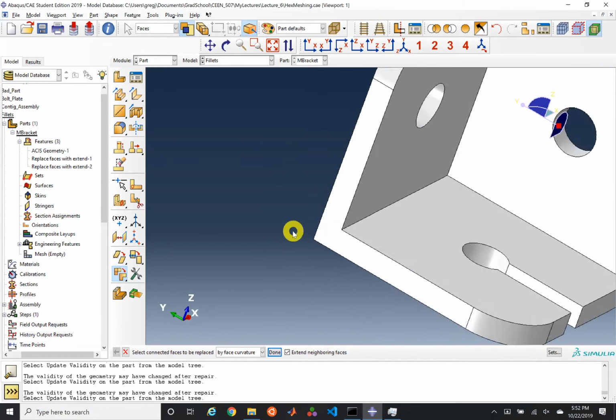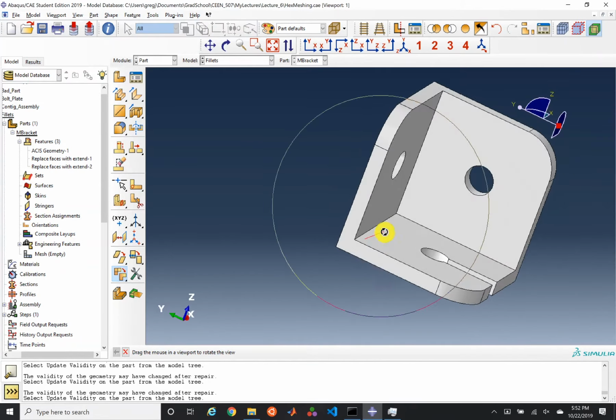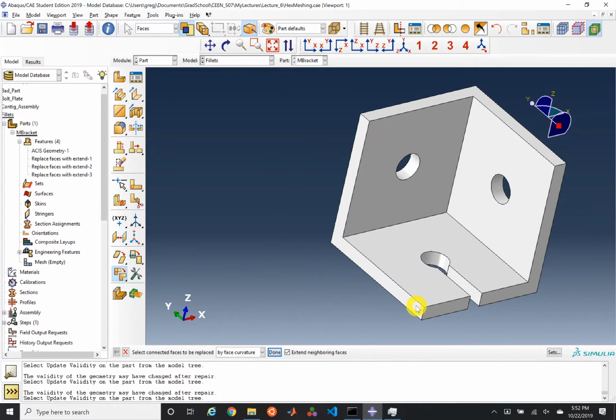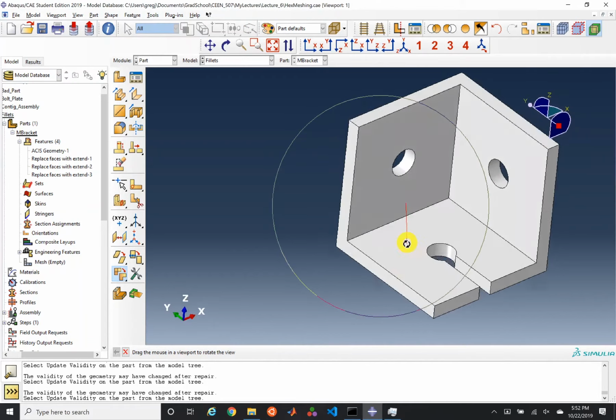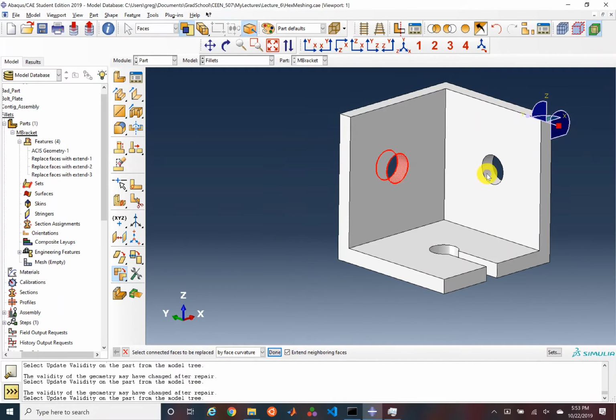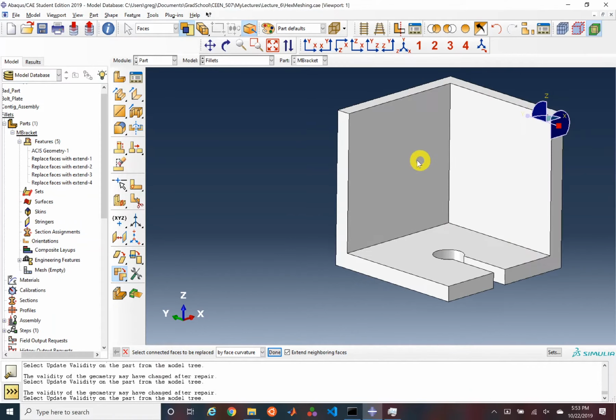well, now I'm going to have stress concentrations here, and this maybe isn't going to be accurate. If I really cared about the, well, I should have probably also removed these fillets as well. But if I really cared about, so here's this fully defeatured model. If I really cared about this deflection, I really do need to have an accurate solution along this plane of bending. I could even have gone a step further and removed these cylinders as well, and then maybe applied some load. But we've already seen a cylinder and a plate isn't necessarily going to be a difficult thing to mesh.